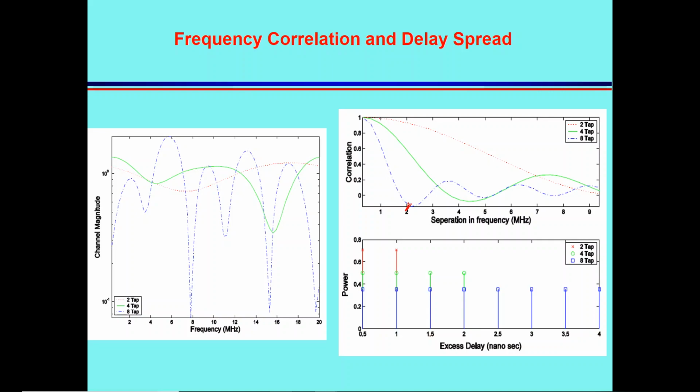This is the coherence bandwidth, by the way, because until this point, you have similarities. After this, you have independent response. While for green, since green varies little, the coherence bandwidth enlarges more, gets wider. While for red, since it's not varying much, it has the largest coherence bandwidth. This is autocorrelation, this is frequency response, and this is delay spread.